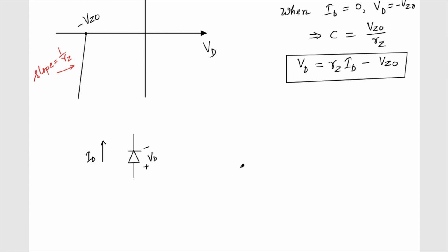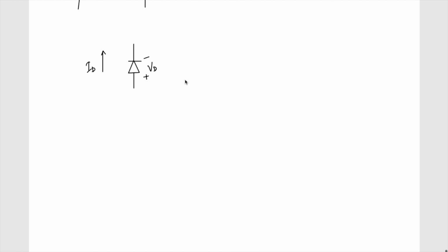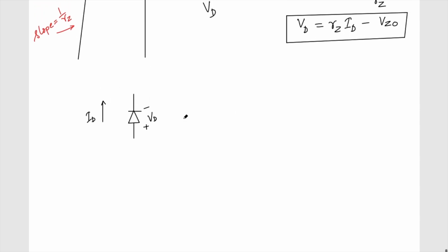But now if you see the Zener diode, the current through the Zener diode is going to go like this, right? So reverse bias current, and then this will be at higher potential compared to this, because it is going to be used in the reverse bias region. That's why for Zener diode, we need to reverse the polarity of the ID and the VD as well.